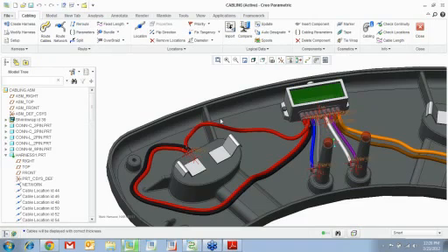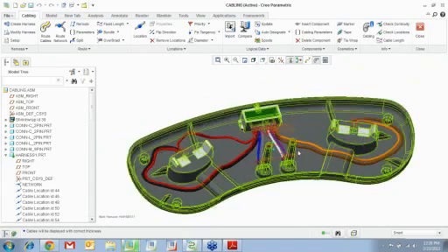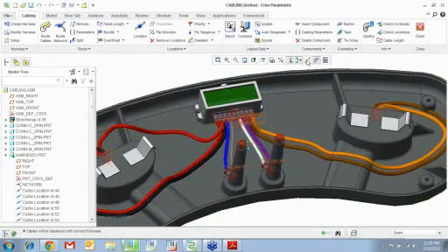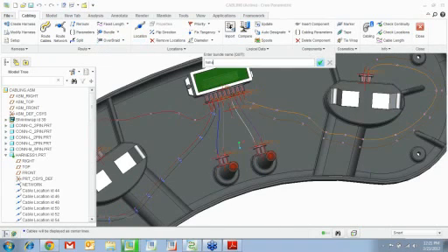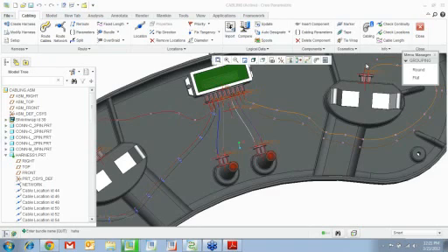Now, that was more of a manual routing of wires. Now we just saw the schematic version of it. You can also add things like spools and stuff. So I go bundle, create a bundle, give it a name, hit enter. Say we want a round bundle. I want to create a little spool, say along the path.